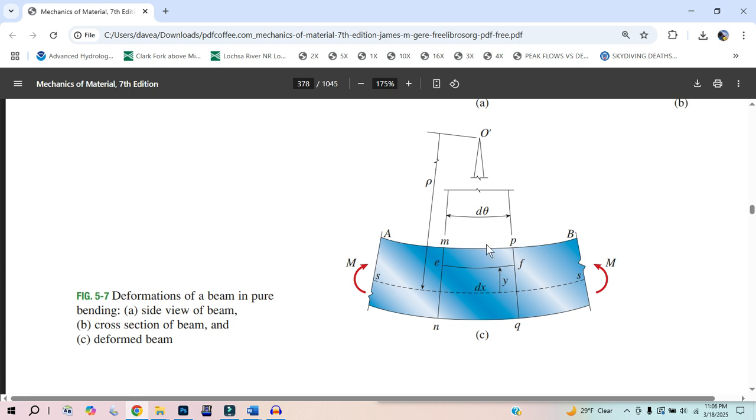So that's the first sign convention that's potentially a little bit tricky. So let's go down here. If I'm pulling on this on both sides, this force arrow would go in the negative direction and this force arrow would go in the positive direction. But both of these are synonymous with stretching this, which we're causing a positive value.